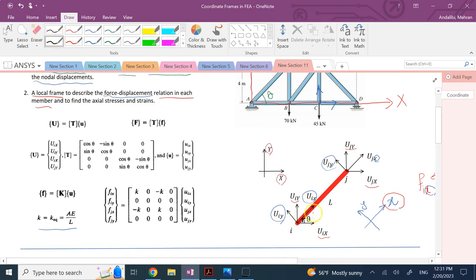Counterclockwise. So the rotation is going to be a rotation Z matrix with angle theta, which, if you watch my rotation matrix videos under the playlist robotics, you clearly find out what a rotation matrix in 2D is about the Z-axis, and that is this guy here that you can see. This is a 2x2 rotation matrix for rotation about the Z-axis and counterclockwise positive angle theta, and a similar thing is shown here. Okay, and the others are 0.